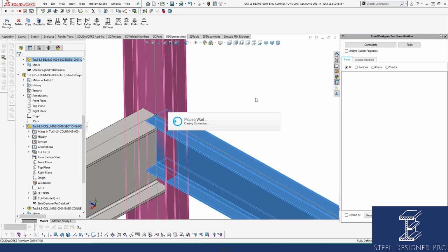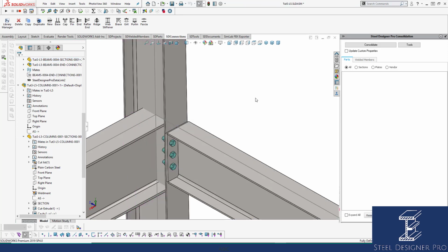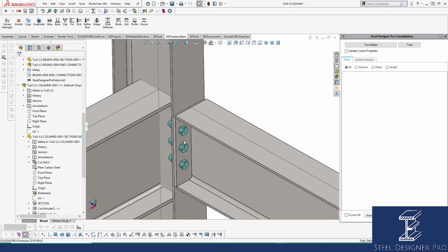to put in a bolted connection that automatically updates the number of bolts, as I mentioned previously, you must understand equations in SolidWorks, and that way the bolts will automatically pattern and the holes will automatically pattern. So let's go down into detail of this connection.